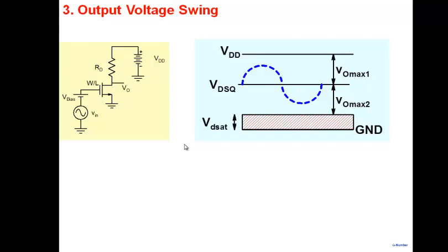On the upper side, we have not put any limit. We have said it can go as much as VDD. But it can get very close to VDD. All that happens is, note that as V0 gets closer and closer to VDD, the net current becomes smaller and smaller. So it's gradually entering into subthreshold now. So we have not put any shaded region there. We are saying it can go up to as much as VDD.